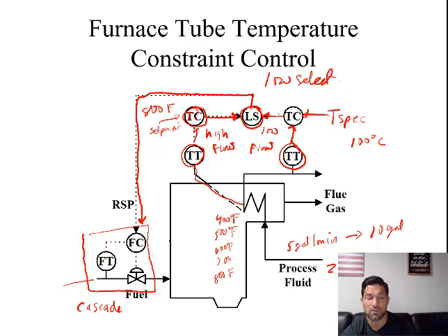Okay, so let's reiterate a couple of things. Under normal operating conditions, when this is at the set point and this is below the maximum value, the signal of the economic objective is lower than that of the process constraint, because the safety constraint loop is asking us to get to our constraint. Okay, so this signal right here would be lower than this signal.